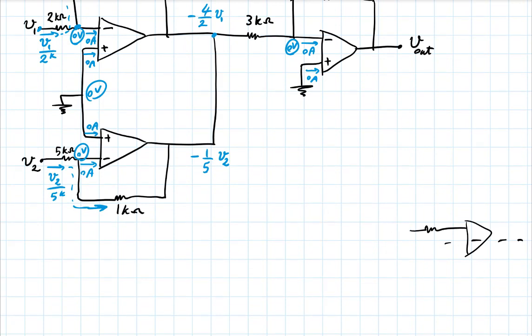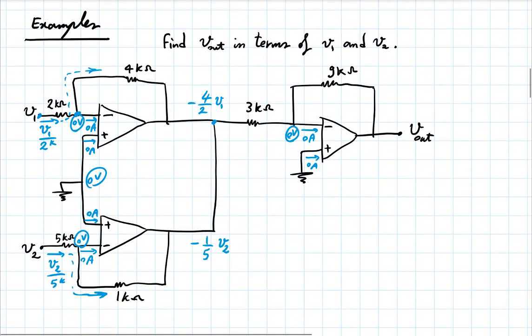It just looks a little more benign. But you see a conflict there. It's a circuit that should not be built because, and this points to a feature of each of those two op-amp circuits, each of the two individual stages, top left and bottom left. You see that in finding the output of the first one, all I had to do was look at the circuit built around the first one. It was acting, or wanted to act anyway, independently of the rest of the circuit.